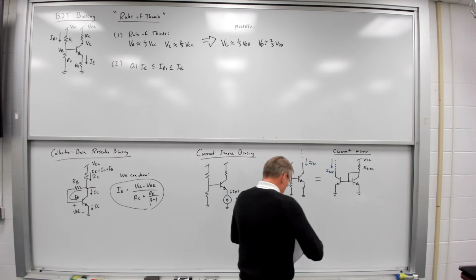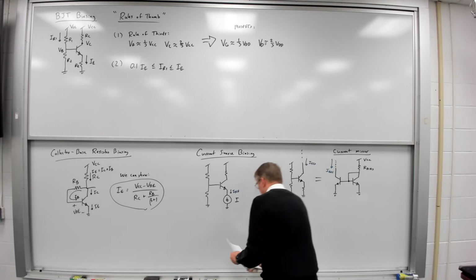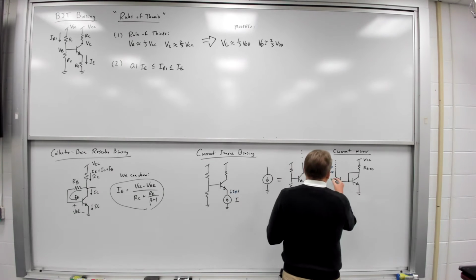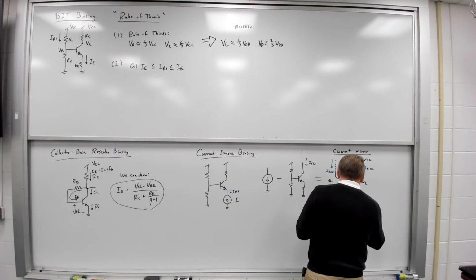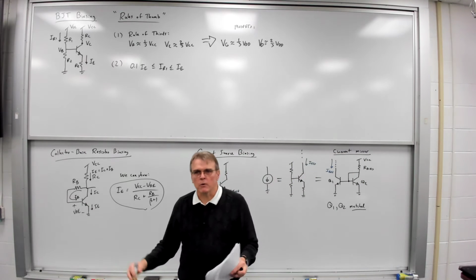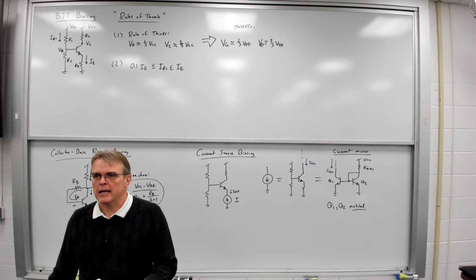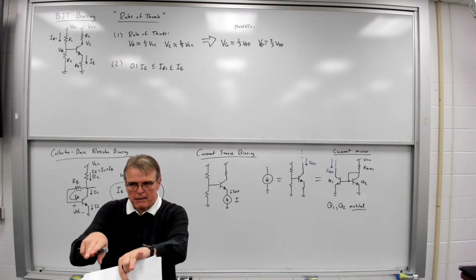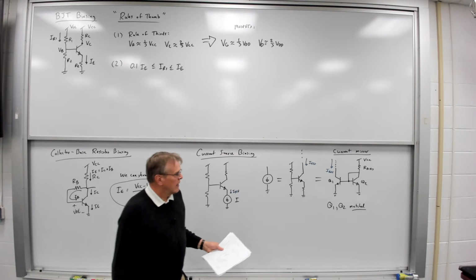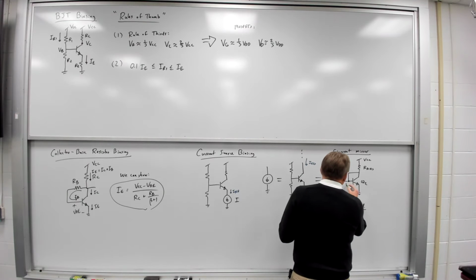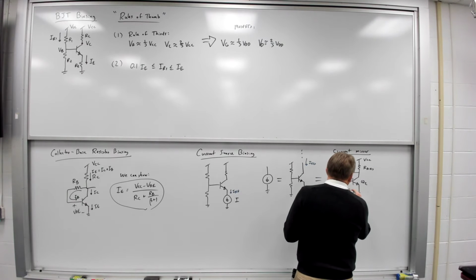In this case, these two transistors, Q1 and Q2, are matched. So whatever beta variations or other parametric variations they have, if you manufacture them together side by side in the same process, those variations will track. And so in this case, again, they're sharing the same VBE. And that VBE, of course, appears up here.